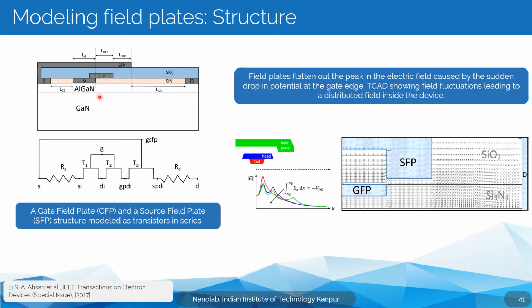There is an entire layer of 2DEG in the entire access region. Then you apply a drain voltage, and this 2DEG layer behaves sort of like an equipotential surface, like a metallic surface. So there's essentially very minimal drop in this 2DEG layer.